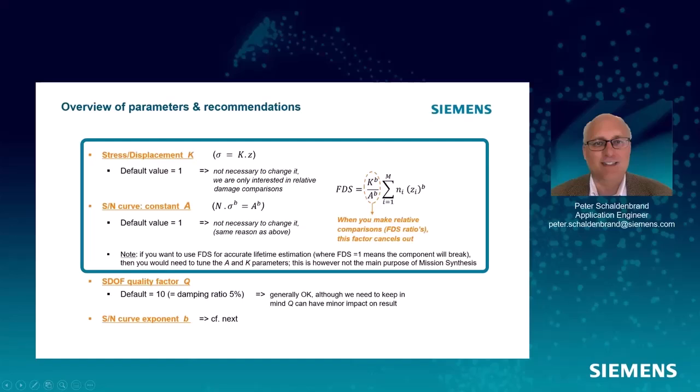What you can't do is take those lines and sum them up to get one damage number across that FDS. If you want to do a strain life or a stress life, you could convert your acceleration to strain, then you should just do the damage calculation in the time domain, not go through the FDS, use this, and then sum the lines.